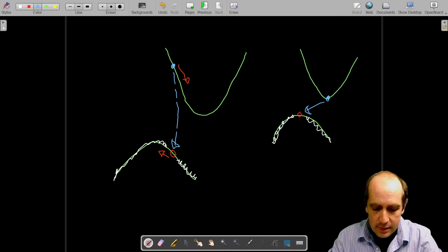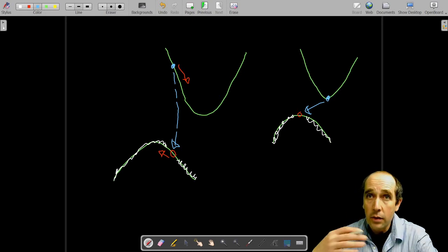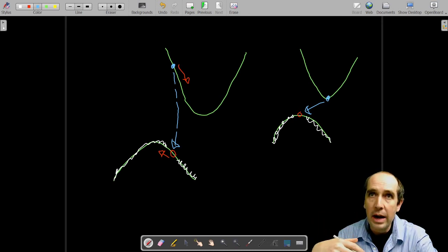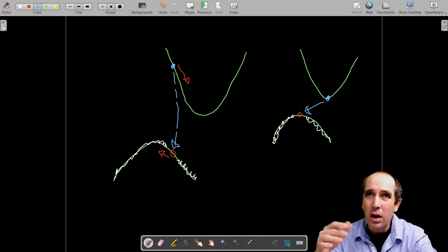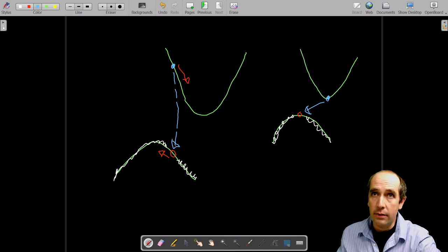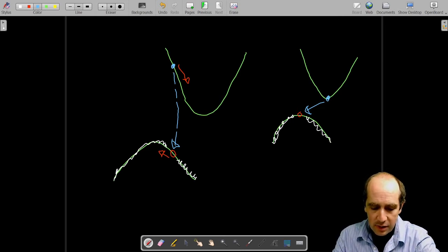So in this sense, the optical properties of direct and indirect bandgap semiconductors are very different, especially in the sense of the recombination. Transitions from the conduction band to the valence band that imply the emission of photons are extremely unlikely in indirect bandgap semiconductors, while for direct bandgap semiconductors we have the opposite case. However, the absorption properties are a different story.